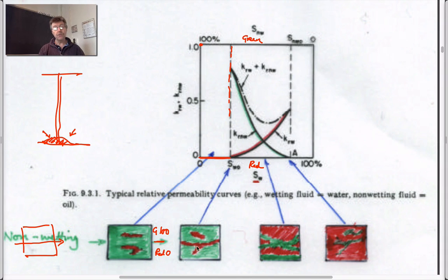As it substitutes more of the water, then all of a sudden you'll be on a curve where this is no longer zero permeability, it's finite. So now you'll suck out some of the red stuff. Out of the total flow that comes out, maybe 5% will be water, and maybe 95% will be green, the DNAPL. And as you keep on removing this, you'll replace it more with water. So the water at some stage will become dominant. In this case you get both fluids flowing.